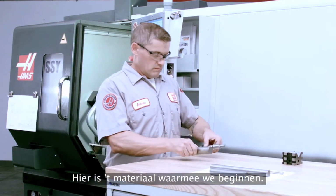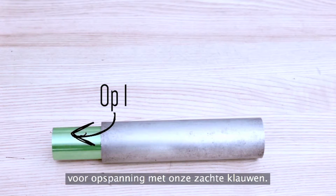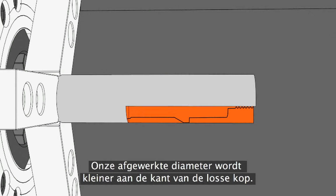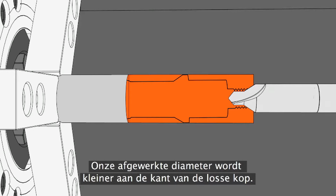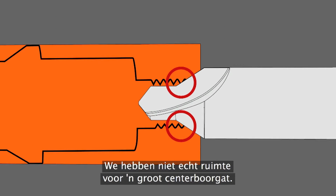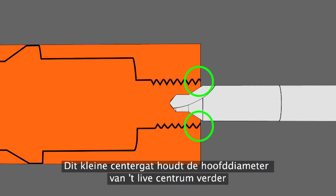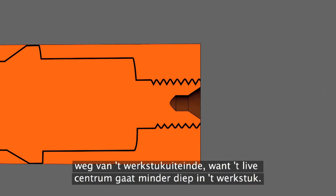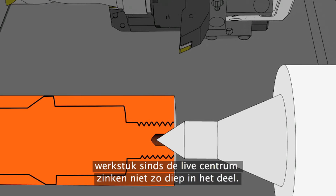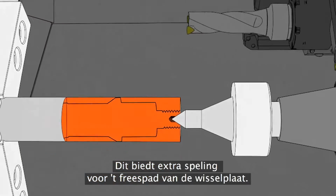Here's the material we'll be starting with. We already completed Op 1, where we turned the bar stock down so we can grip it with our soft jaws. Because our finished diameter will eventually get small at the tailstock end, we don't really have room for a large center-drilled hole. So we'll choose this small number 3 center drill. The small center hole will also keep the live center's main diameter farther away from the end of the workpiece, since the live center doesn't sink as deep into the part. This provides additional clearance for the cutting path of the insert.